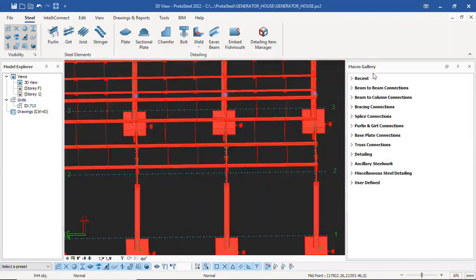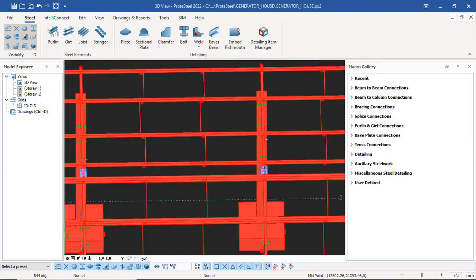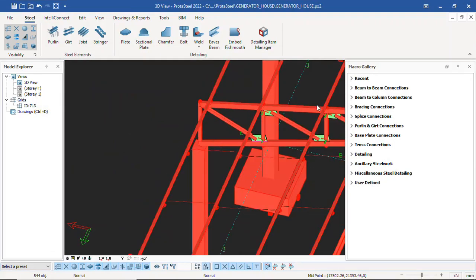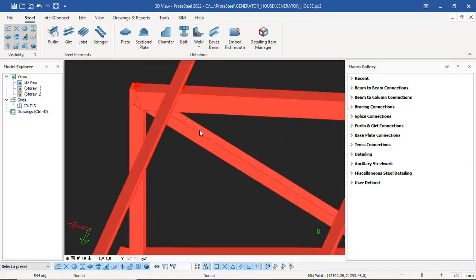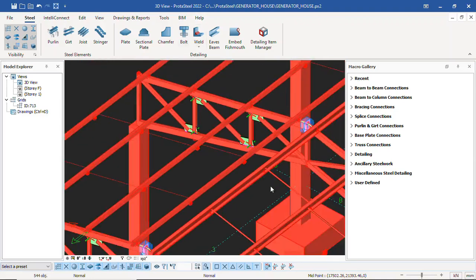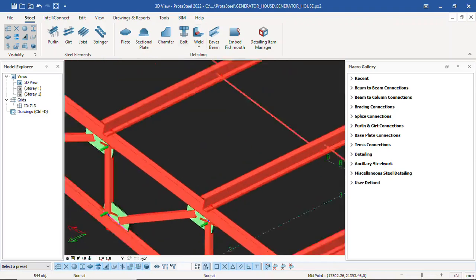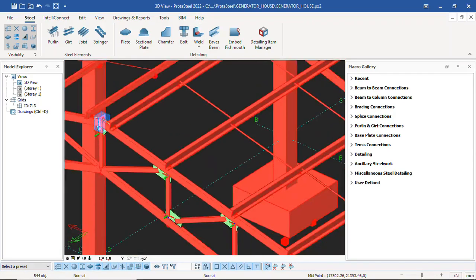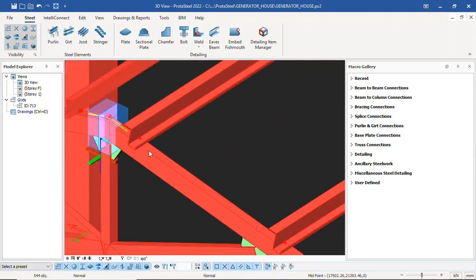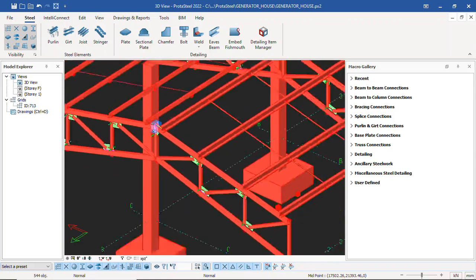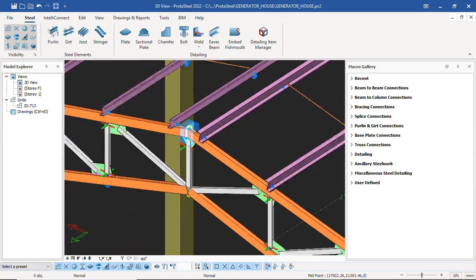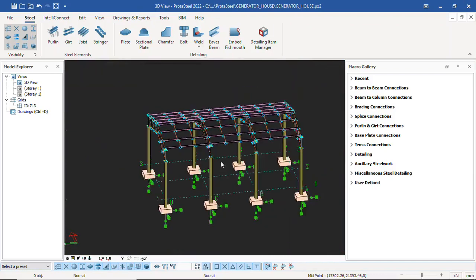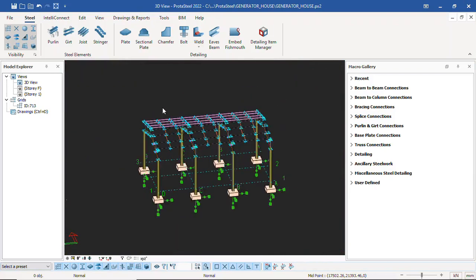The reason why your brace cannot connect, the Z connection, maybe they have not created the connection. Prota has not created the connection for Z pole line. So if you choose any other type of pole lines, it will easily connect. That's the reason why it has not connected. And in my next video, I'll show you how you can manually create your own connection in Prota. You can see other ones are connected, all your truss connections are connected. So the next thing you do now is to